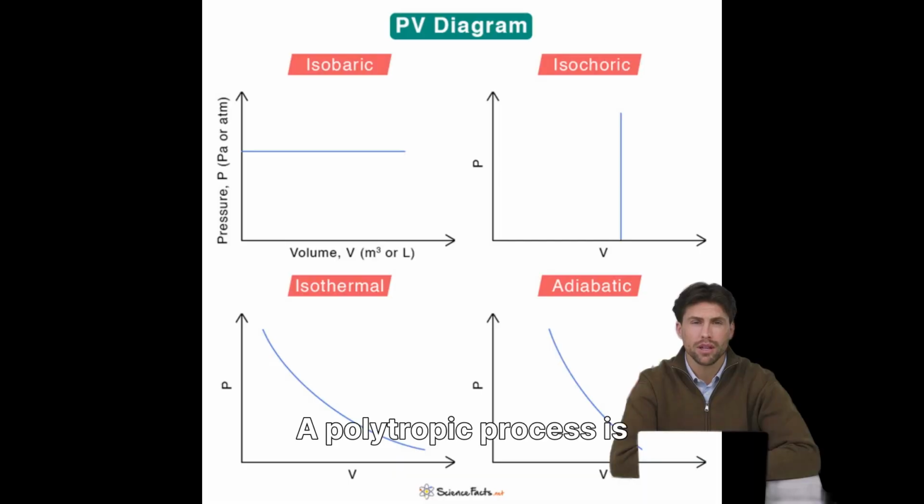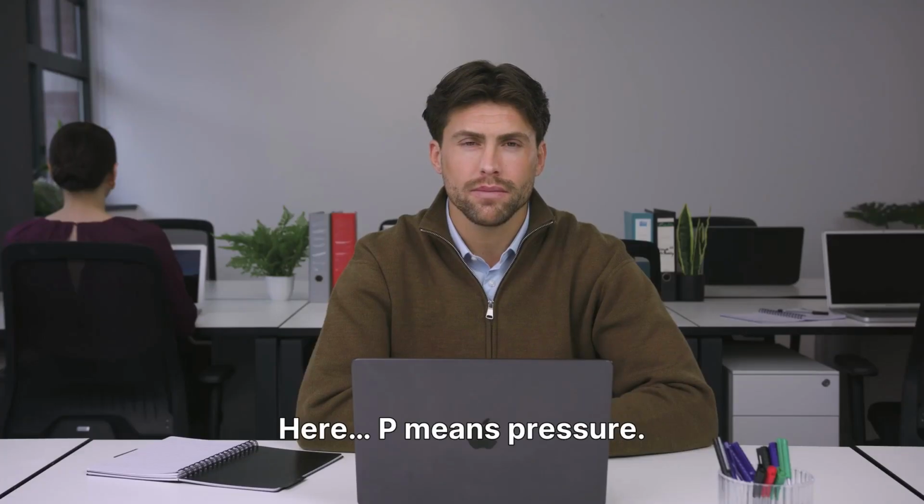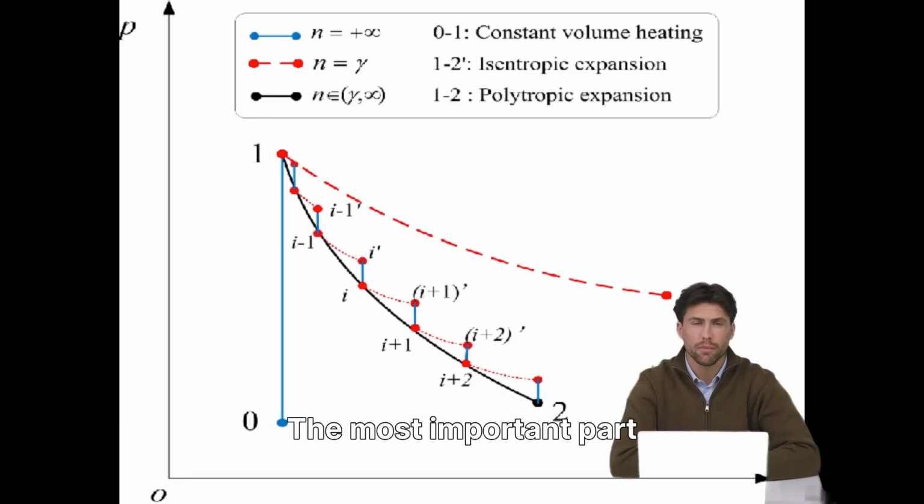Now let's understand the meaning. A polytropic process is a thermodynamic process where pressure and volume follow one rule. This rule is written as P multiplied by V to the power N equals constant. I will repeat. P times V to the power N equals constant. Here, P means pressure, V means volume, N is the polytropic index. The value of N decides the type of process. The most important part is the value of N. Different values give different processes.